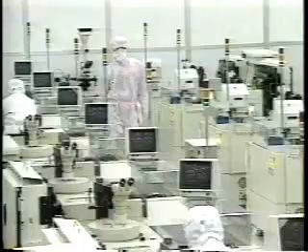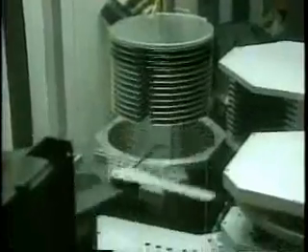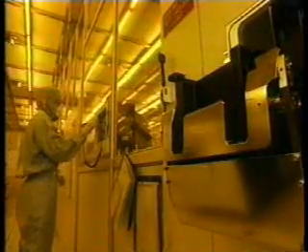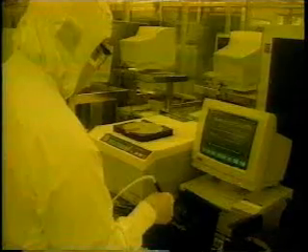One important aspect of understanding the cost of the product is to understand the cost buildup of the product as it flows through our factories. The cost of a product very early is basically just the raw materials and a low amount of labor content of a wafer as it comes into the factory, a wafer that may cost $40 for the raw substrate and is going through 1 or 2 mask steps. Again, the cost we've invested at that point is relatively low. After that wafer has been through the wafer fab process and been through 20 or more mask steps, we have upwards of $500 invested in that.